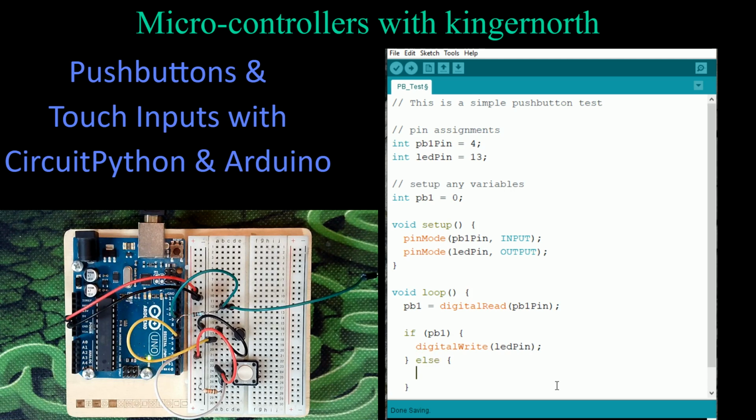And I'm going to give it a secondary choice here. So this will be digital write. And in this case, again, this is LED pin. Oh, you know what? I've got to put more into that other comment, because you know what I've forgotten here? If we're going to write something, not only do we have to assign the pin, but we've got to assign the condition. So I better tell this one it's going to be low. So guess what I better do to the other one and fix it up? I better make that one high.